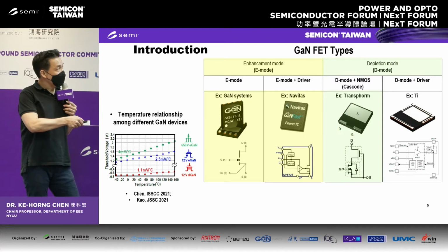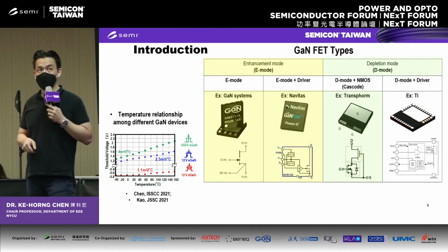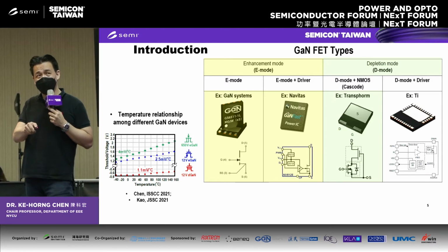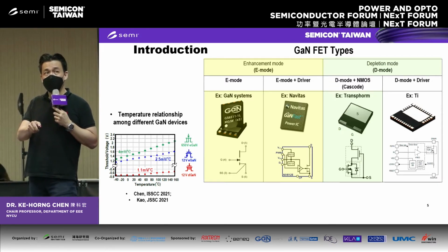In contrast, for the TI products, the gate drive signal is applied on the gate of the GaN. It means the operation frequency can be higher than that of the MOSFET, so it has the advantage of high switching operation and high efficiency.